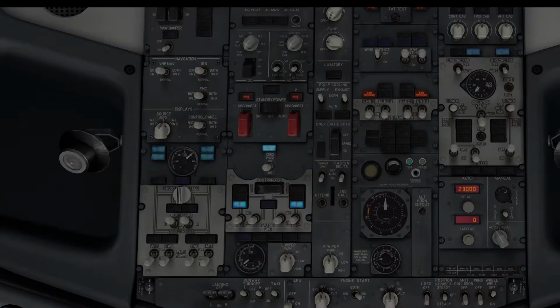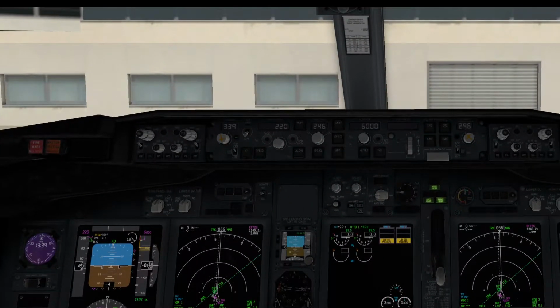Now, go back here. We can select auto brakes, rejected takeoff, flaps 5. QNH was 1023. We check the altitude, 15 feet, a little over 20, and that's about right. 22 will be too low. Let's say 23 is good.